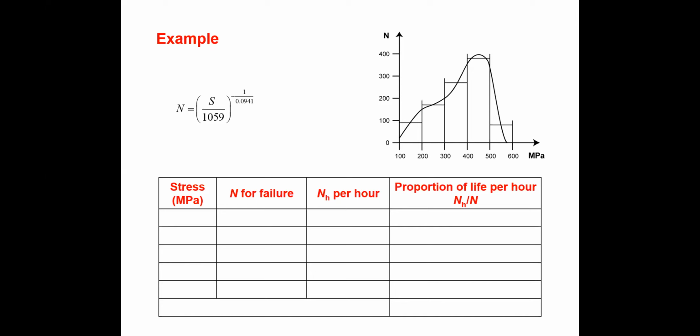So above the endurance limit you can use it; below the endurance limit, you can't use the Miner rule, because there is no point applying it as there is no damage to the sample. So if you apply over stressing only, we need to apply the Miner rule.